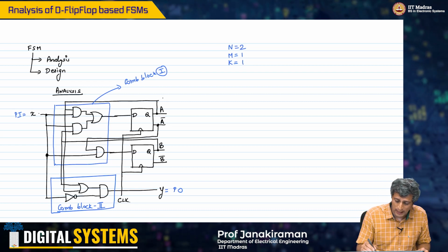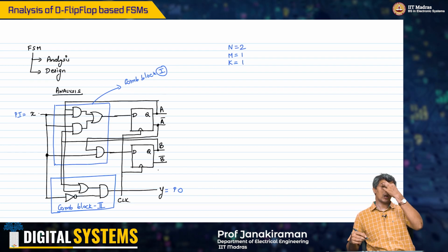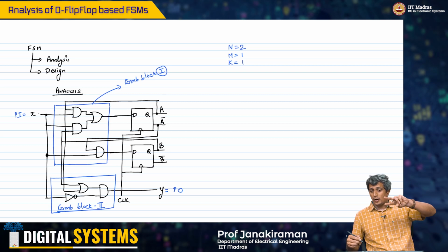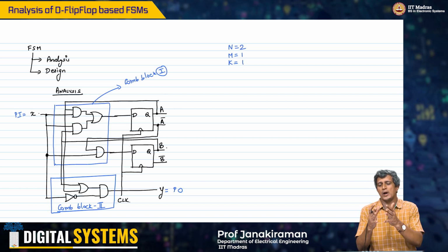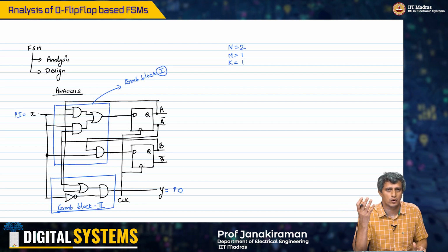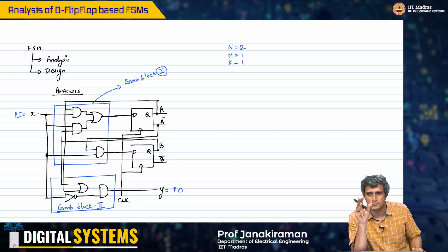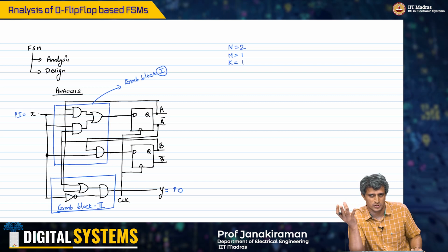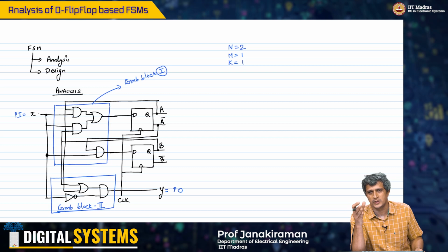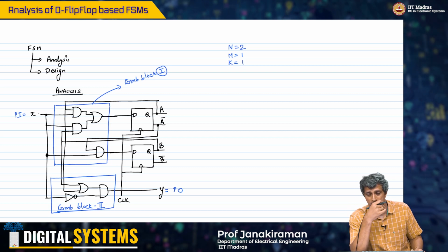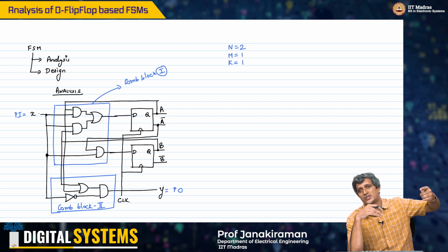So of course we have, because see what matters is not just the combination of A and B. So if you look at the system here, you have A comma B representing two outputs of the flops, right? They can take only 4 different values, 0 0, 0 1, 1 0, 1 1, but what we are interested in is actually the sequence, right?